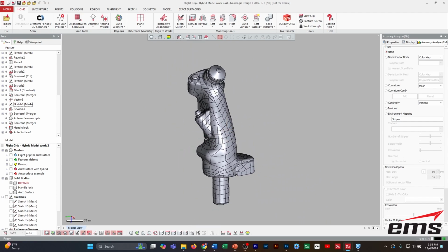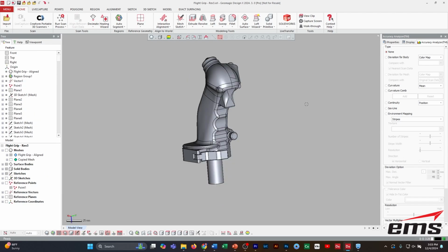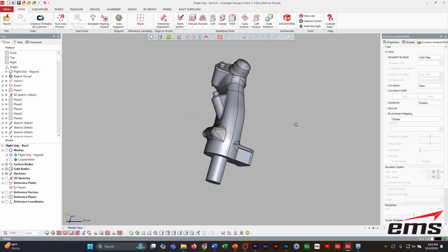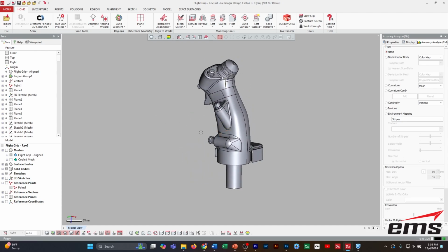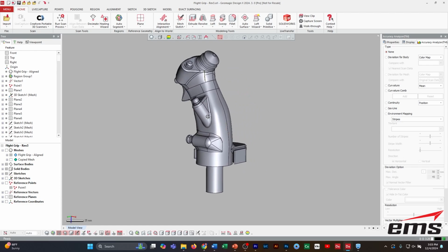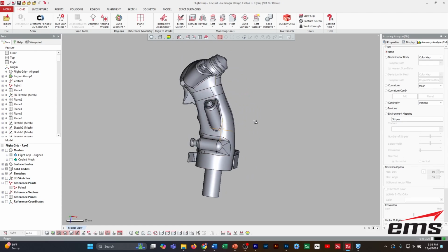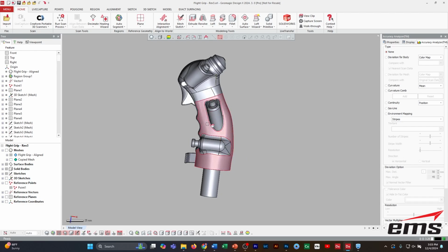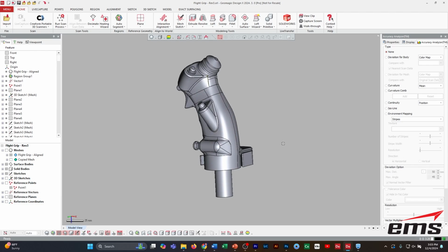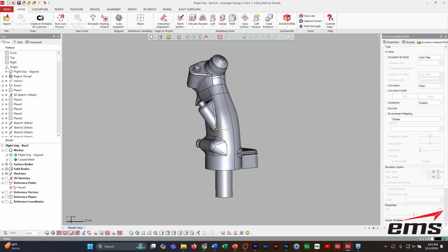The last one we'll look at is what we call that smart surface. So the first thing you'll notice on the smart surface here is how different it looks, okay? And instead of all those just kind of random four-sided surfaces, you can see here the surfaces are much more intelligent. There's fewer of them. And that's because it's driven more by geometry, such as sketches and splines and so forth.